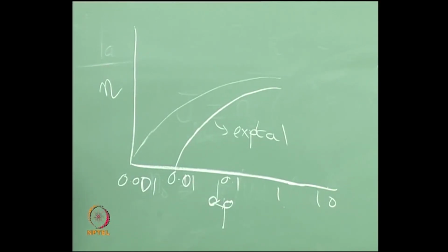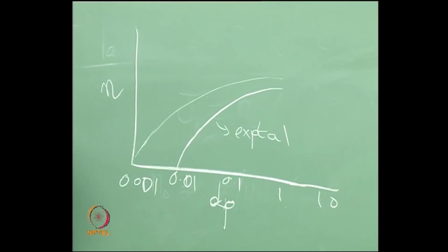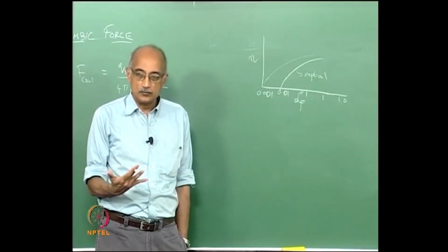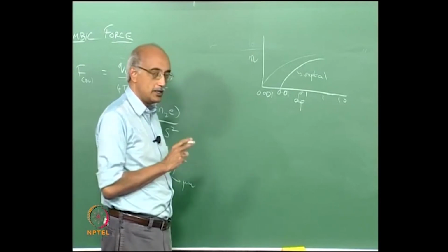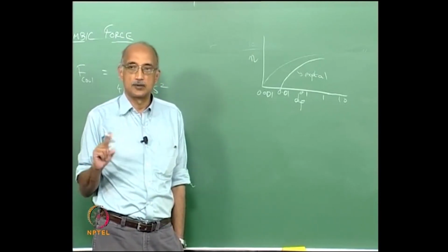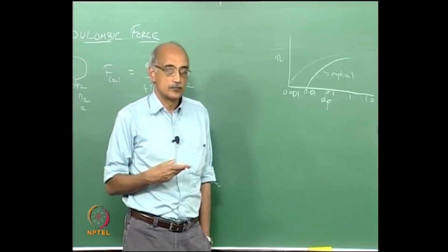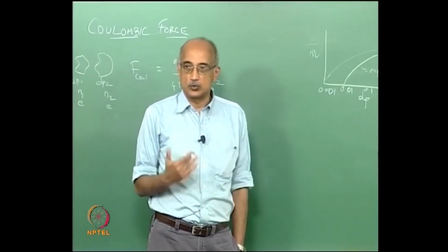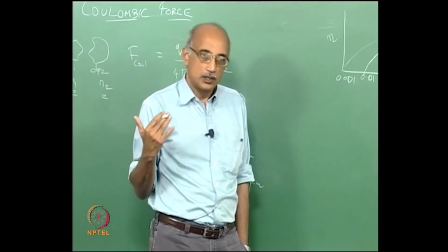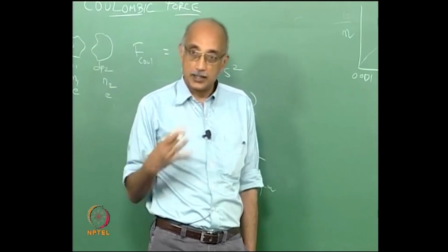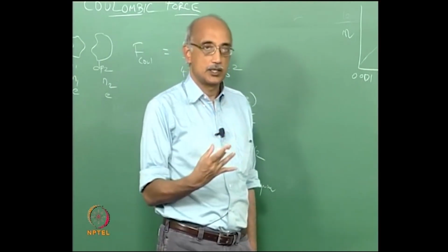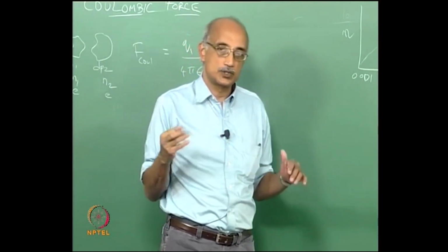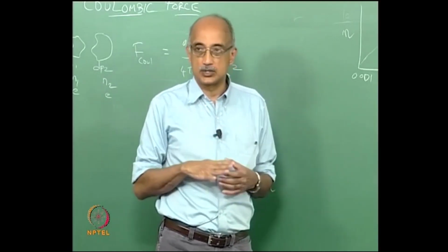So the charging effect in a neutral field is important primarily for particles that are larger than roughly 10 nanometers. If the particle is in the nanometer range, 1 to 10 nanometers, you can kind of ignore charging effects unless there is a charge field that has been induced to deliberately set up a charge on the particles.